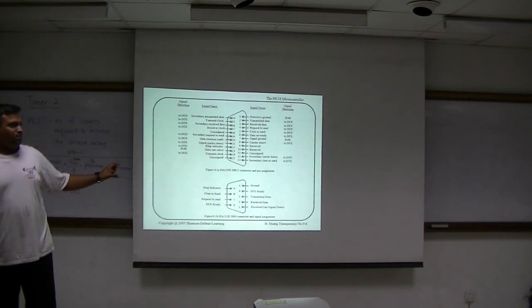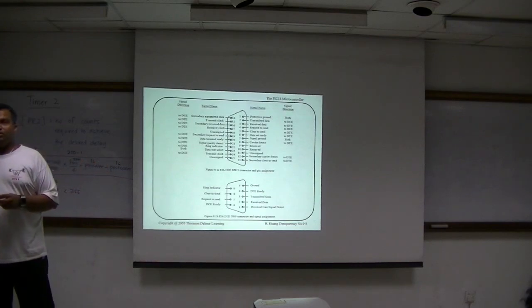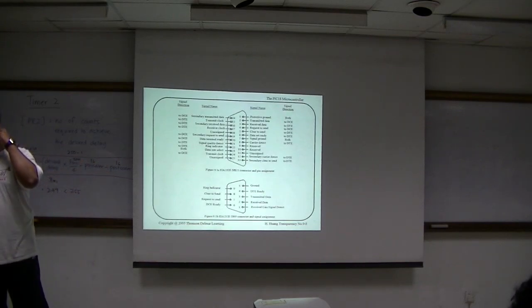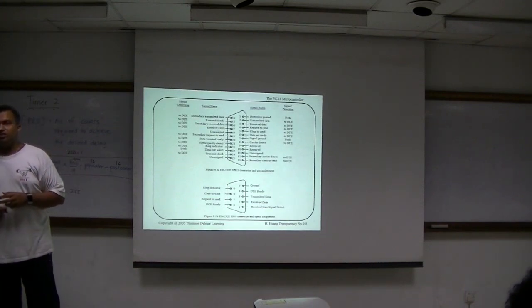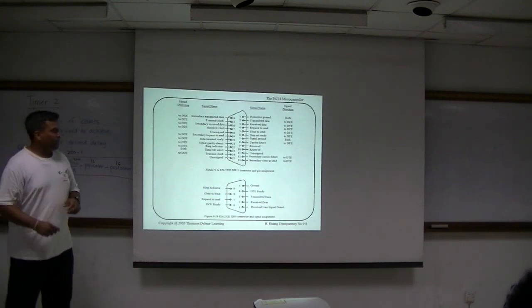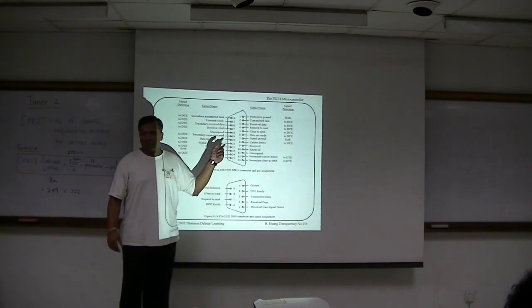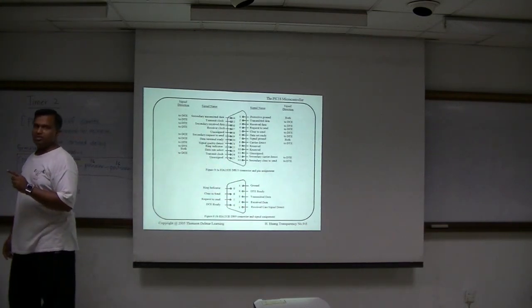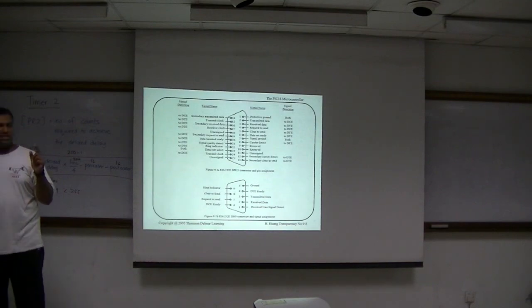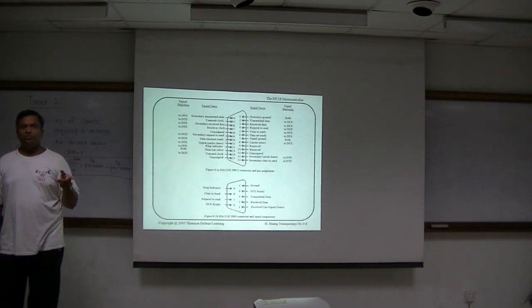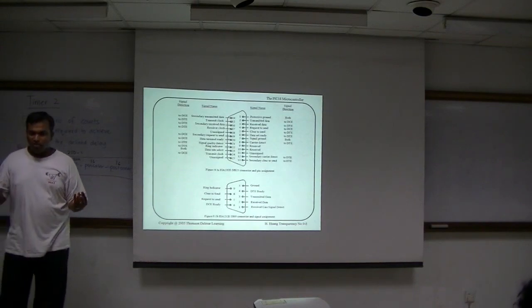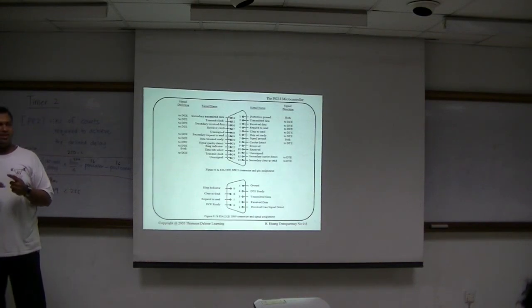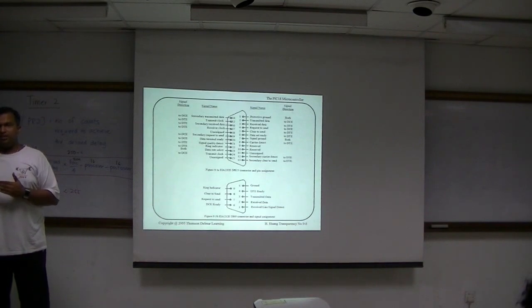Now you need to connect from the microcontroller to the computer. Now there's a difference in logic. The computer is not working on 0 to 1 volt. It has a different voltage level. The port at the computer, this port here, operates on that voltage. Whatever voltage you're sending for logic 1 and logic 0 will be in that voltage range. So from the microcontroller to here, it needs to do the voltage translation.